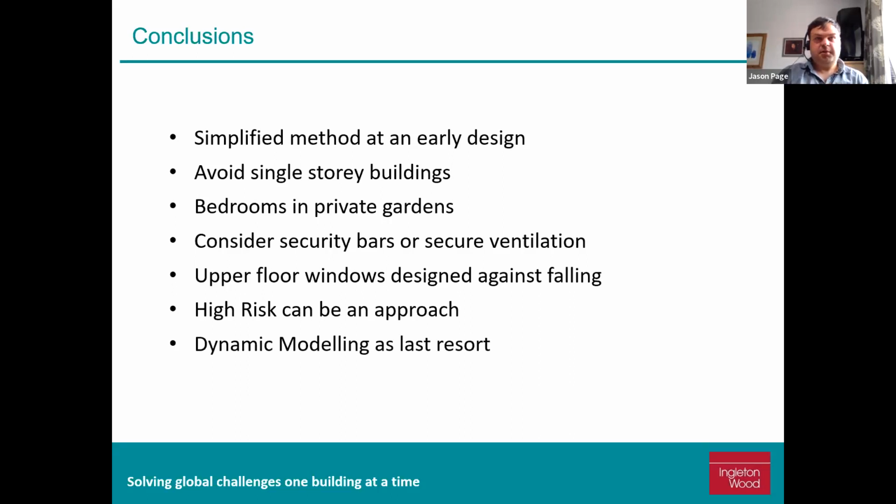And lastly, I would treat dynamic thermal modeling as the catch-all solution if you don't like what the simple methodology is telling you. It allows you to be much more flexible, but don't think you can design anything and get away with it. It still requires good solar control principles in place. So with that in mind, I'm going to finish here and hand over to Thomas McCosker to talk about this and give you a bit more detail.